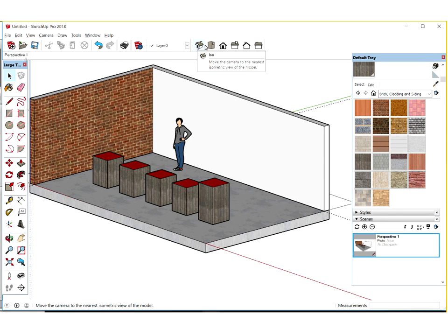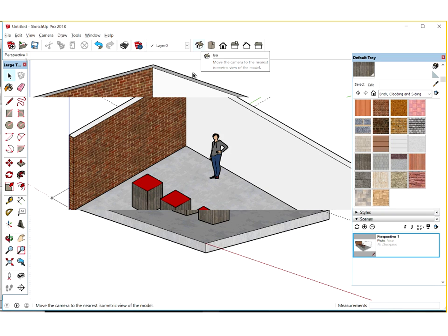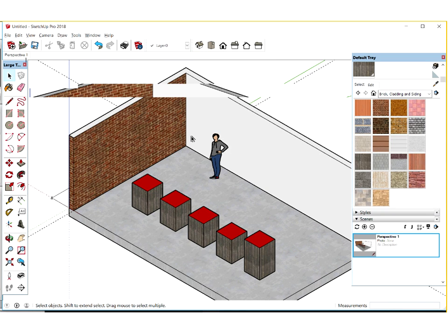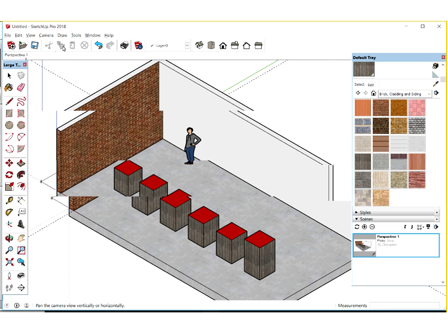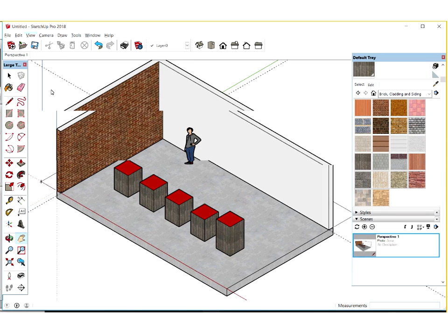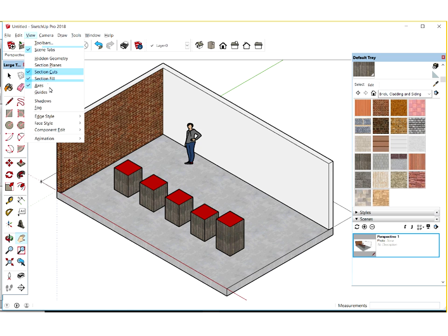And speaking of isometric views, we have an ISO button in our standard views toolbar, the little row of houses at the top. That's now a true isometric with 30-degree edges and vertical lines there. So we can save our isometric scene there if I want to save that one as well. You can always pan and zoom to make your scene fit the screen nicely as well. I might actually just hide my guides and axes for that particular view as well.